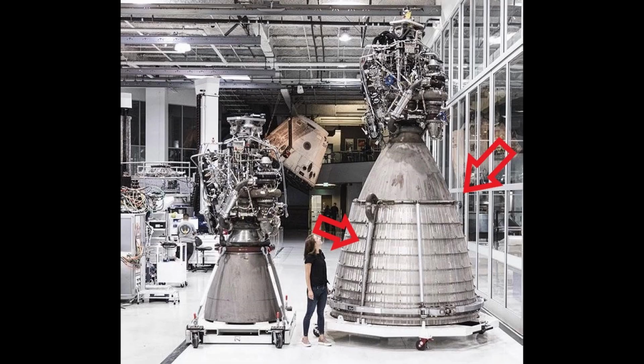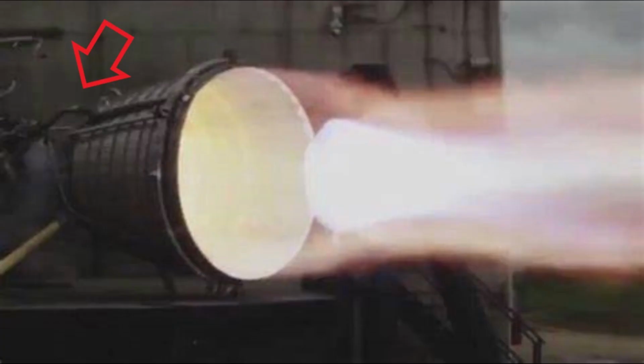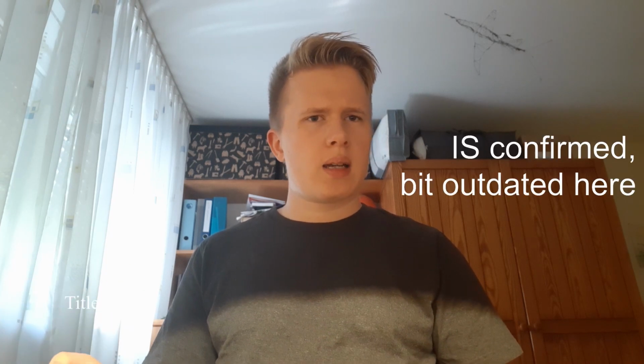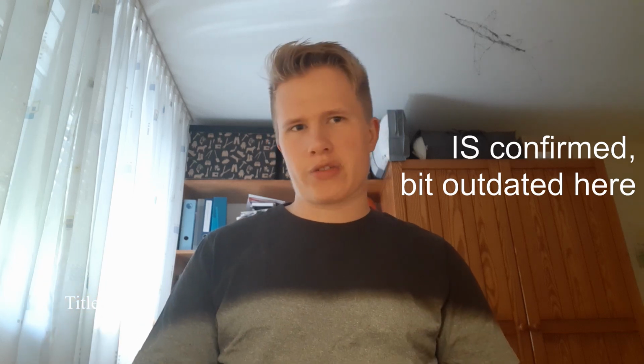On the other hand, there are structures visible on a vacuum Raptor that look like pipes. There's one ring about in the middle of the nozzle and a second one at the very bottom of the engine. Between them, there are many smaller pipes connecting the two rings. And there's one big pipe coming from somewhere around the combustion chamber that leads into the upper ring. Such a piping system clearly points towards regenerative cooling being used on the airvac as well, although that isn't finally confirmed yet.